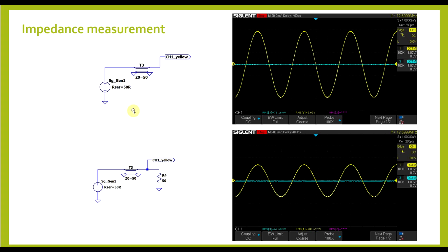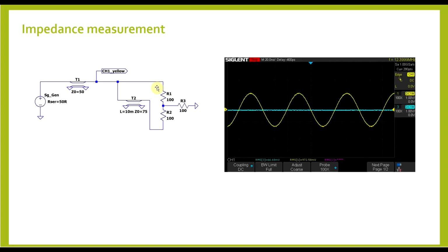Next, to confirm the input side impedance of our balun, I measured the signal that would arrive in the balun when there is no load, and then when there's a 50 ohm termination. So with an open line, we are measuring about 2.02 volts RMS, and into a more or less ideal 50 ohm termination, we have half this value, so 980 millivolts. And next, when we reconnect our load, the voltage present at the input is a close enough 972 millivolts. So even though the transmission line used for the balun is 75 ohms and the termination is 200, the entire structure behaves like a 50 ohm load. So the impedance transformation is working as expected.